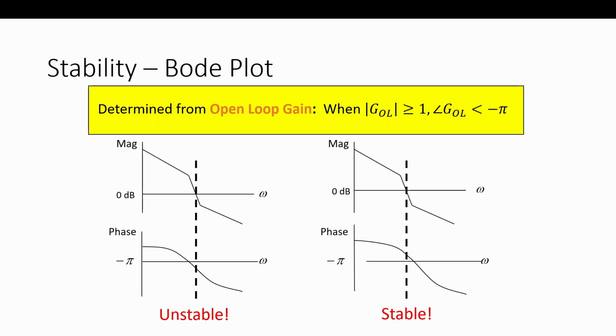So here, what I want you to see is the idea of the Bode stability criteria: if the magnitude is 0 dB, which is a gain of 1, or lower by the time the phase passes 180 degrees, then that would be stable. Kind of makes sense, right? We have gain and 180 degrees of feedback and positive gain, and that's reinforcing and would be unstable.